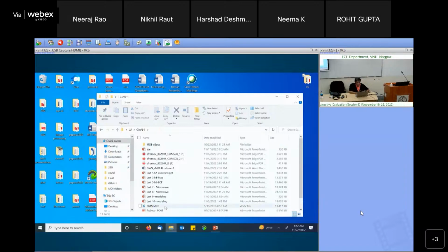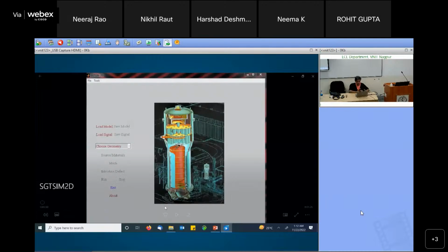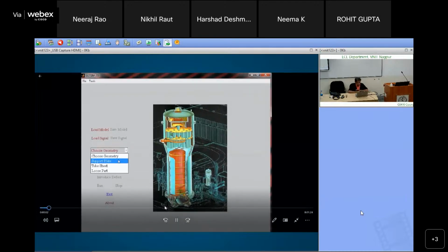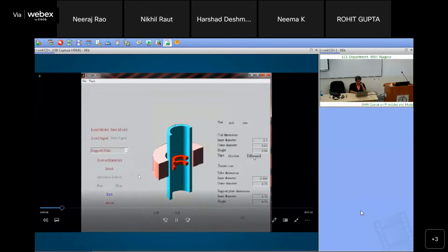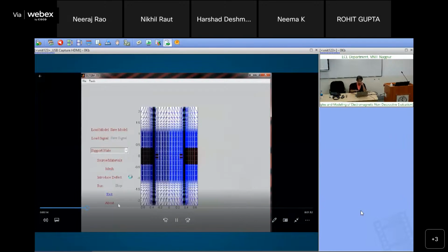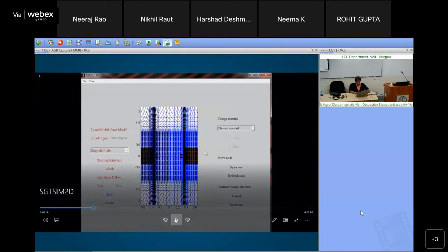So this is the reduced vector potential formulation, 2-dimension, axisymmetric geometry, triangular elements. We choose the geometry, which is the support geometry. The support plate is there. So this is the geometry: support plate, differential coil, and the tube wall. Then you mesh it. You provide all the dimensions, and that's what the code generates as this mesh.